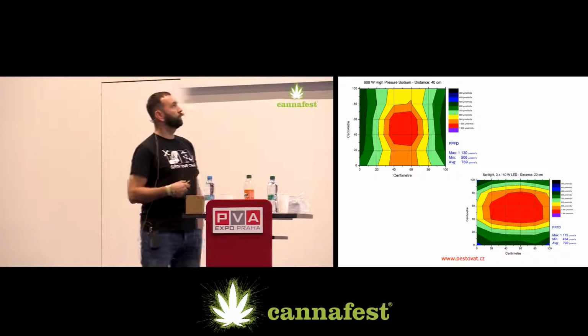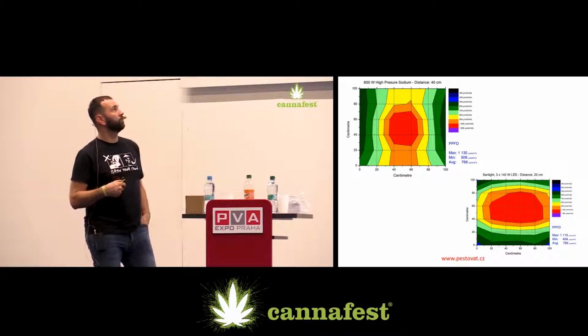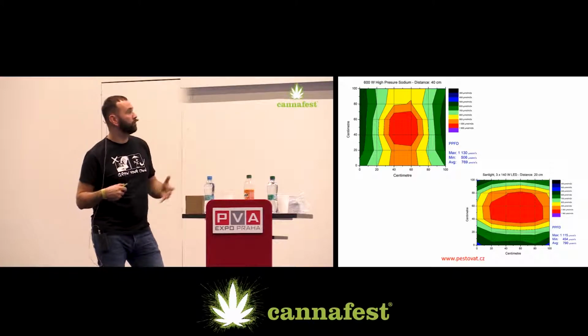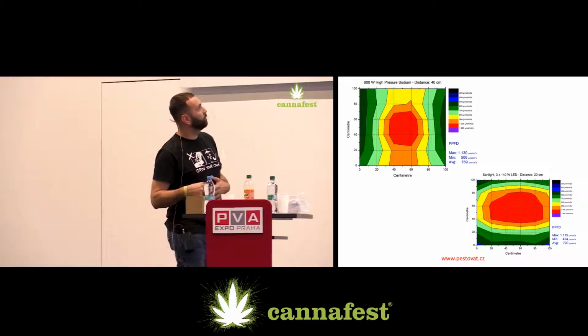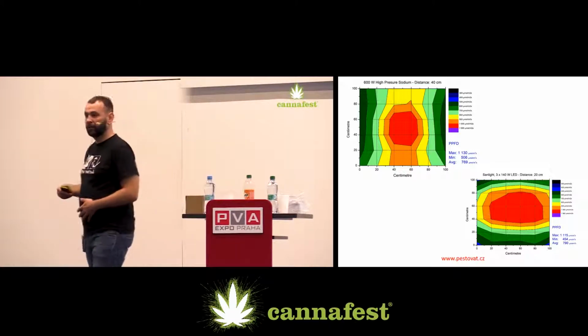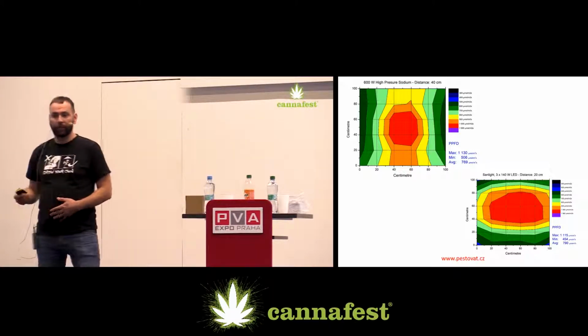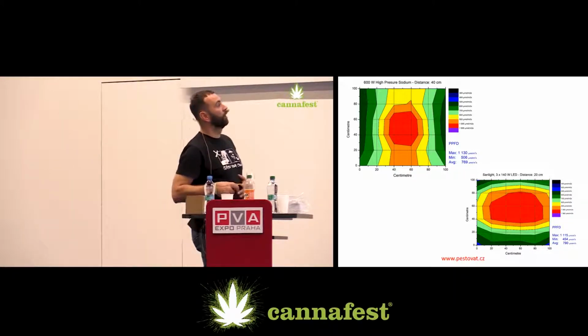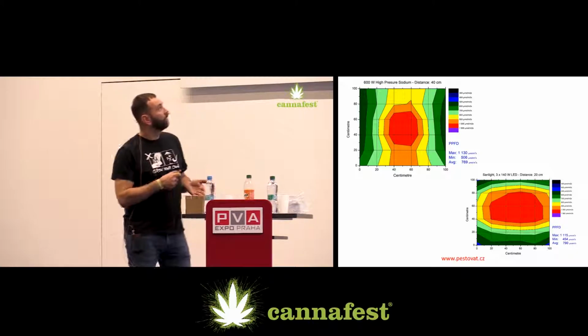It's only several percent difference, but we can demonstrate that if I have a classical ordinary 600 watt sodium lamp used by most people, there's no problem replacing that with a 420 watt LED module, or rather using 3 modules of 140 watt each.